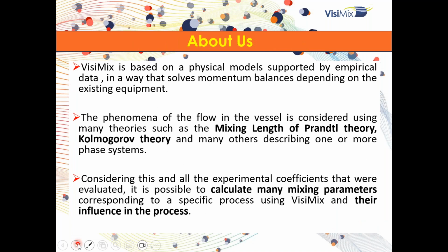So all of this we explained before. For people that don't know, we solve the momentum balance, the velocity, we adapt the theories of flow mechanics, and once we know it, we're able to calculate power per volume, mixing times, eddy size, and more. And after that, if you want to know more, you need to add more data. Until now, we added data about liquid-solid, liquid-liquid, gas-liquid. We had a simple reaction. Now in this software, we will be able to upload many reactions. I will show many materials, and we have a database for reactions and materials that maybe will help you progress with your solution.